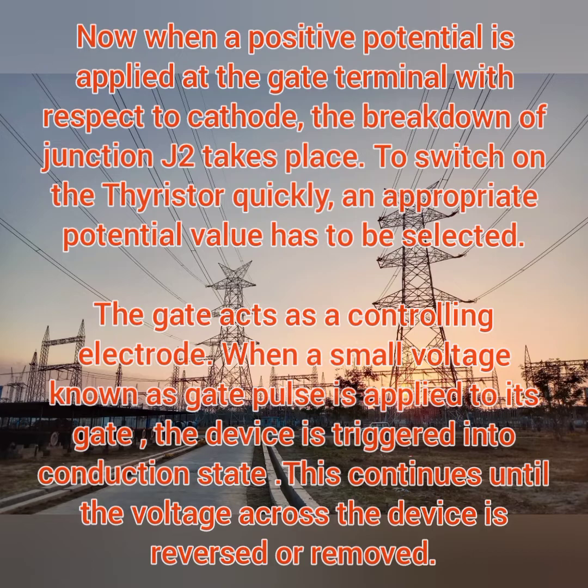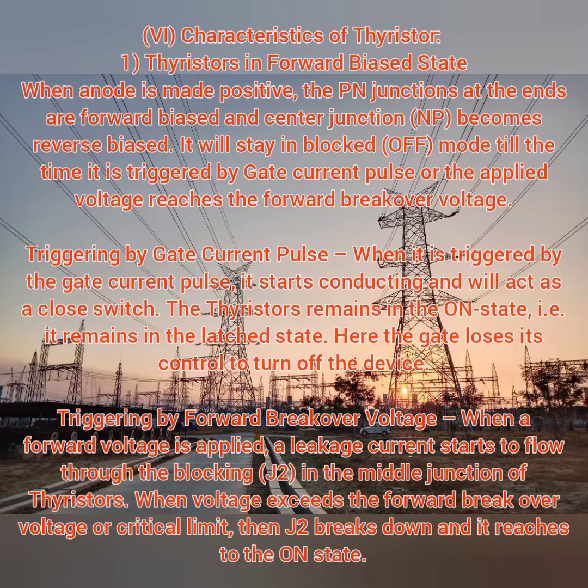So commonly we are going to use this gate pulse for controlling your thyristor, input and output. Then V-I characteristics. For the thyristor, there are two types of V-I characteristics. One is your thyristor in forward biased condition and the second one is your reverse biased condition.